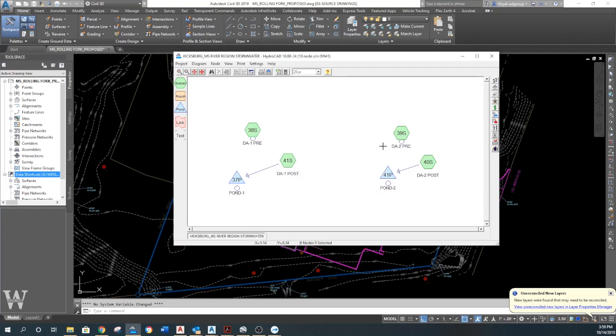Okay, and this is probably going to be my scenario. I'm going to have two ponds, so I'm going to have a couple of drainage areas that I work with. We'll walk through that as we go. The very first thing that I need is an IDF curve for this site. I don't have one for this particular site, so I need to find one. This is the way I do it.